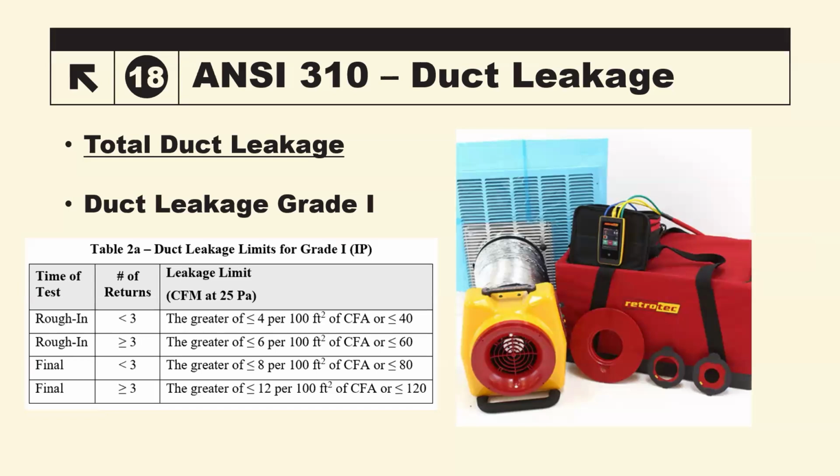But also, if you have systems that are fully encapsulated in a foam house and everything's within the conditioned space, well, everything minus up to 10 feet of ductwork is inside the conditioned space, then the standard doesn't require it to be tested. In the 2021 and moving forward, it is still code required to be tested, even if it's all in conditioned space. But if you're in a system, an area that's 18 or 12 or 15, then it doesn't have to be tested. So this is also excluding that as long as 90% of everything is inside the conditioned space.